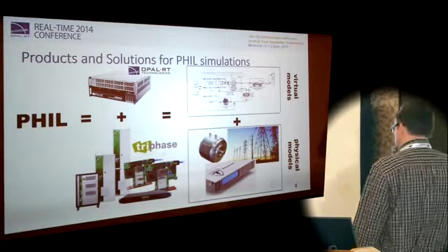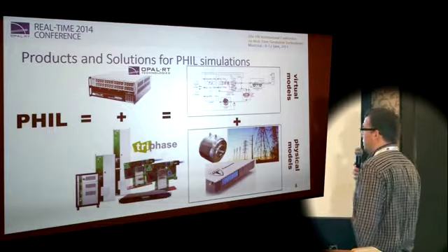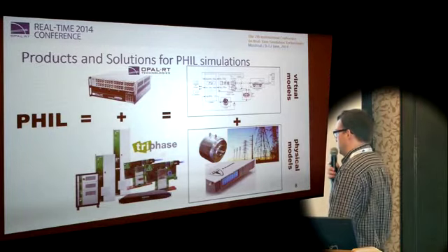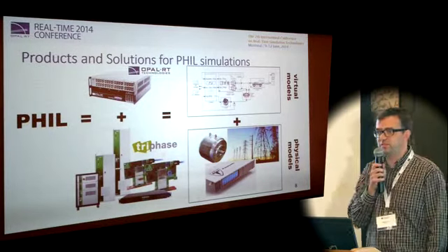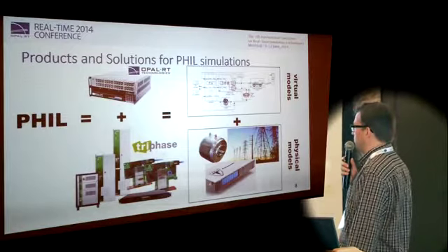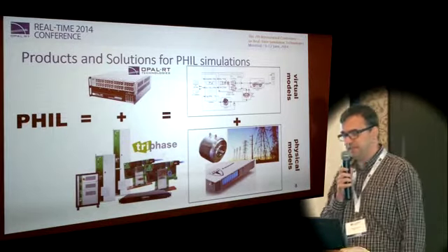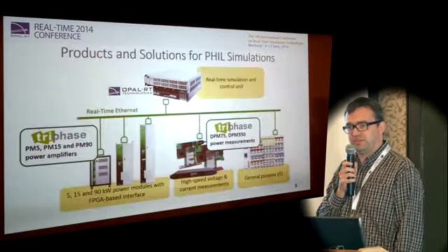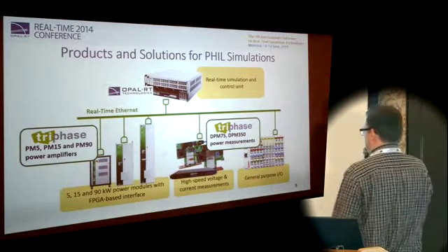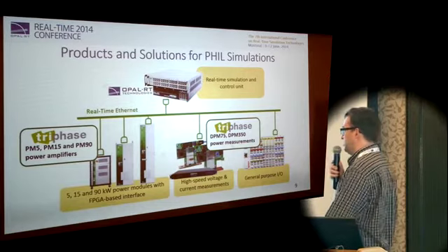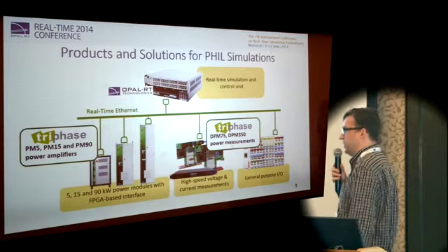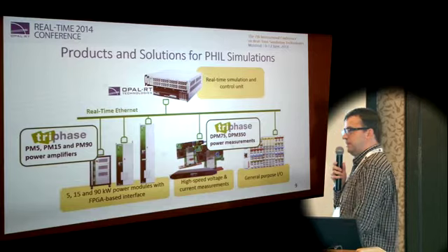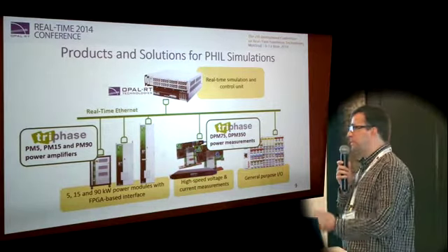The network technology that we use to interface between OPAL-RT and our power amplifiers is, and there's a word that has disappeared, it should have been EtherCAT. EtherCAT is actually an open standard field bus technology that allows you to connect a whole bunch of IOs in quite an easy fashion. So you simply daisy chain.